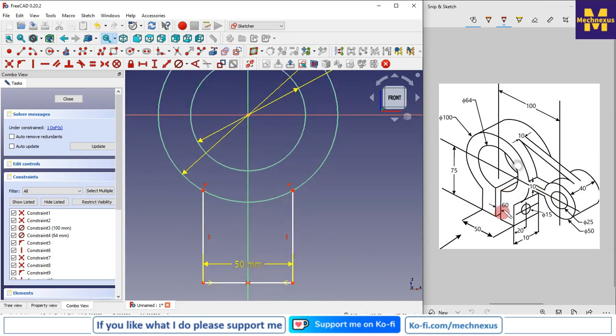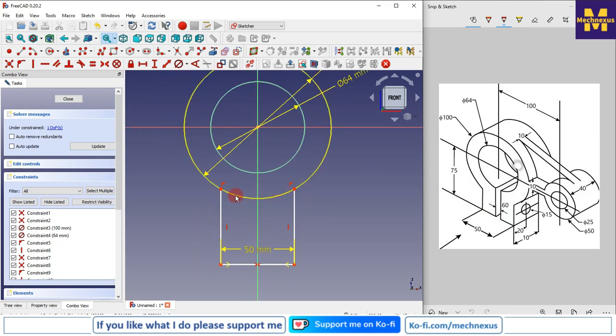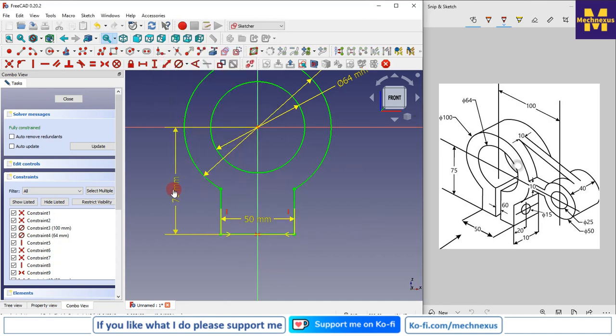And here is a cut, which is a material removal process, so we will do it in a separate sketch. And now I will remove this geometry because this is not part of our sketch. So I will select the trim and trim it, and now we will find the height from the center. So here it is 75. I will select these two points and give the vertical dimension 75. So here our sketch is fully constrained.